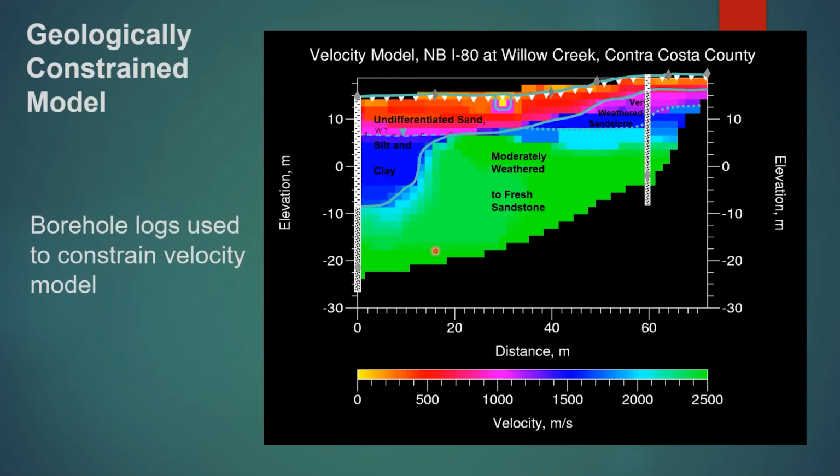The geologic correlation is presented here as an overlay. We had a water table in this borehole. We didn't have a water table in this borehole, which is very interesting. And you can see we have this high velocity, moderately weathered to fresh sandstone in this area.